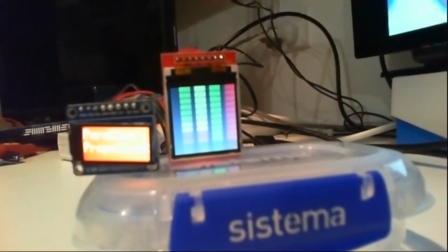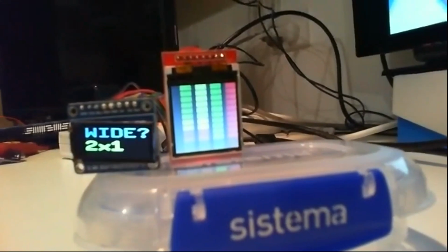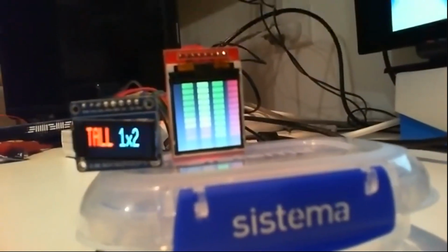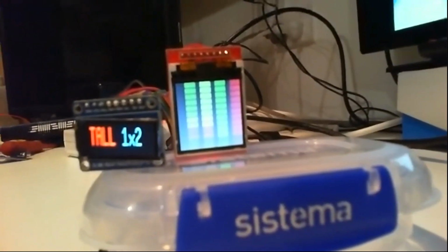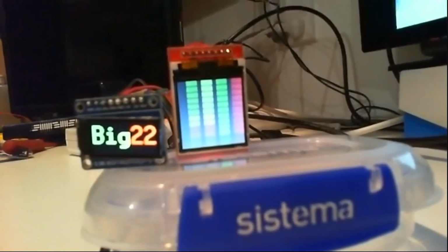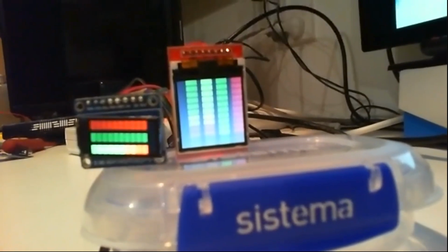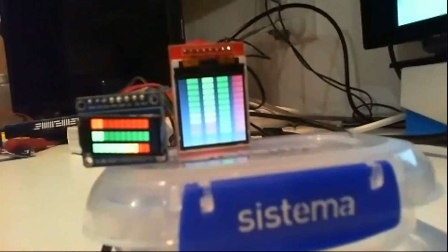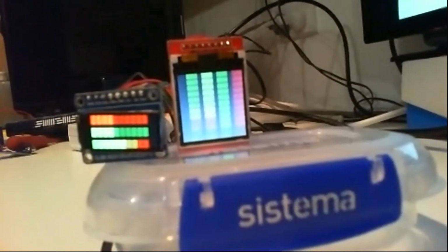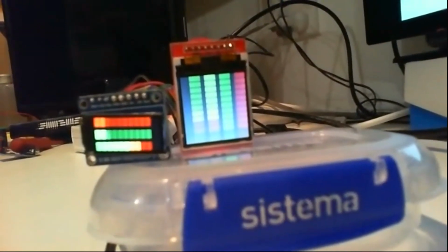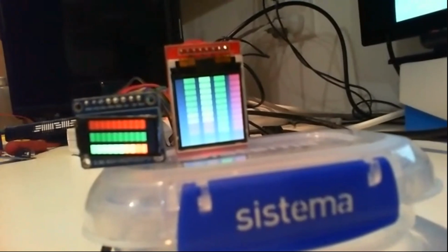It has actually got a built-in scroll function in the hardware, but it's a little bit clunky to use, and it's a little bit weird because you've got screen rotation modes. So I've done my own one where I just have my own buffer that I do my own shifting and manipulation, and then I just blast that buffer out. But yeah, the P1 font, that comes up okay.